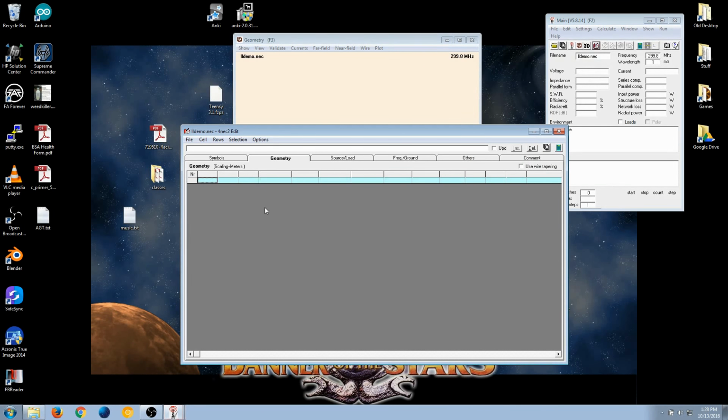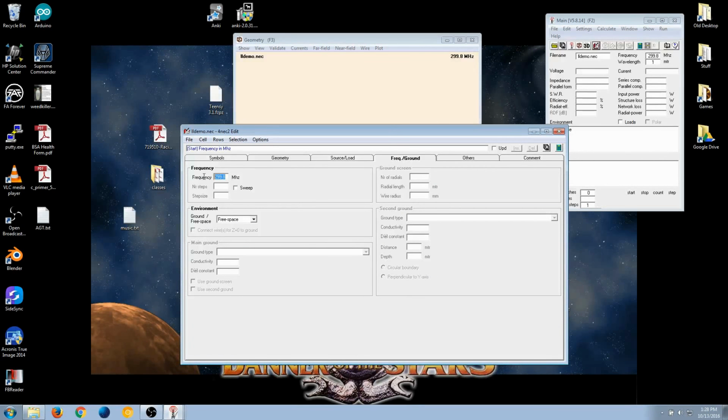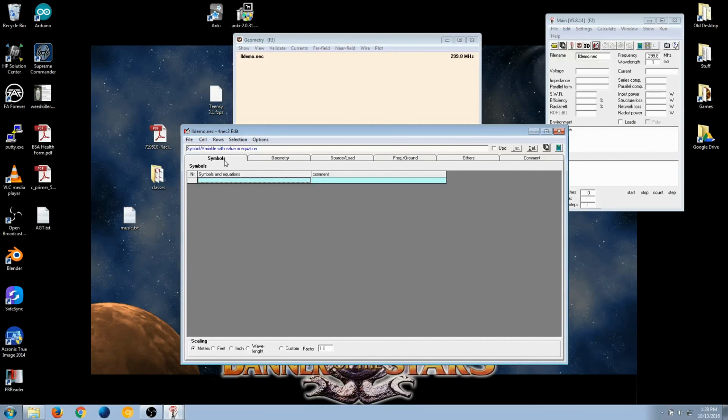We're going to open up our editor window, go into frequency and ground. We're going to set that to 27.2. Let's go to real ground. Moderate's fine for this. And save. Okay. Now when I start modeling, I don't put in a lot of wire data like you do.